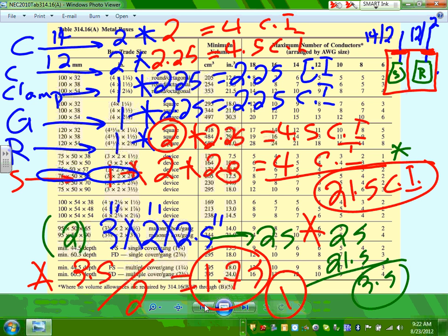Yes, sir. Was he bringing them in there to add a device in the future, or was he just running them through? In this case, it's meaningless bringing one conductor, really. There's no room to add anything else. What was the purpose of him running the conductors through there? The only thing I can think of is, what if I want to put this device into an isolated ground? Could be an extra for a multi-wire, isolated ground. Multi-wire branch circuit, splitting this receptacle into 2 circuits.